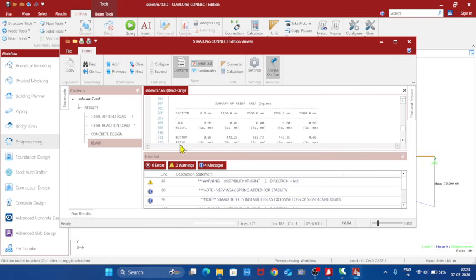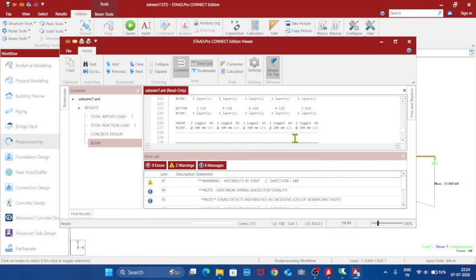The top reinforcement, bottom reinforcement. Usually we do not require any reinforcement at the top. However, two numbers of 12 mm dia bars are used as hanger bars to have ease for construction or for providing stirrups. This is 2-12, 4-12, 6-12, 4-12, 2-12. So actually at the center only we have maximum bending moment. Therefore 6-12 is required at the center of the span, and that could be gradually reduced to 4-12 at these points and 2-12 at the ends, because bending moment gradually decreases to 0 at the supports and is maximum at the midpoint. So this type of reinforcement can be provided for economical reasons.